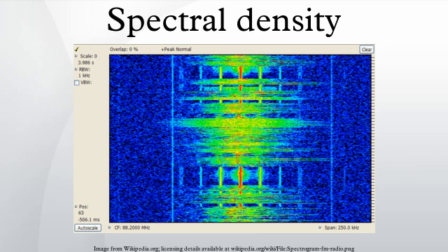Explicitly, we have. Using such formal reasoning, one may already guess that for a stationary random process, the power spectral density and the autocorrelation function of this signal should be a Fourier transform pair. Provided that is absolutely integrable, which is not always true, then the Wiener-Khinchin theorem makes sense of this formula for any wide-sense stationary process under weaker hypotheses, does not need to be absolutely integrable, it only needs to exist. But the integral can no longer be interpreted as usual. The formula also makes sense if interpreted as involving distributions instead of functions.